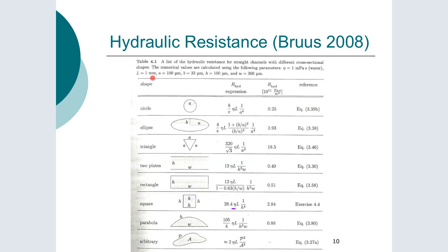Note here that it is using the symbol eta. I think it's eta anyway. My Greek isn't very good. Eta for viscosity, whereas we tend to use mu traditionally. That's just a European thing. So mainland Europe, they tend to use eta sometimes, or mathematicians tend to use it. So anyway, always check the nomenclature to be clear.